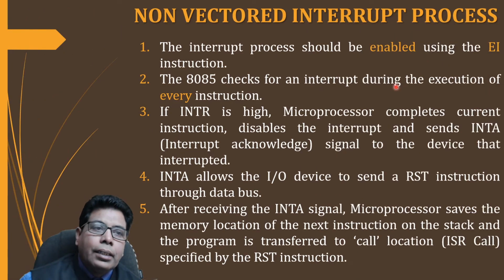Then let us discuss the non-vectored interrupt. Here we'll concentrate only on the INTR interrupt, because that is the only non-vectored interrupt. Again, the first step is that the interrupt process should be enabled using the EI instruction. Then the 8085 will check the interrupt during execution of every instruction,